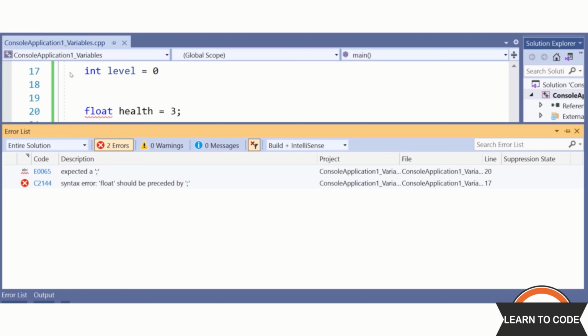And with the debugger mode in Visual Studio, we can get a lot of information about what's going on even on the Unreal side, because sometimes when you're running a project in Unreal, the project can just crash without much of a good explanation why. If you're running the same project but in debug mode, then Visual Studio will often give you a much more detailed explanation about what went wrong.